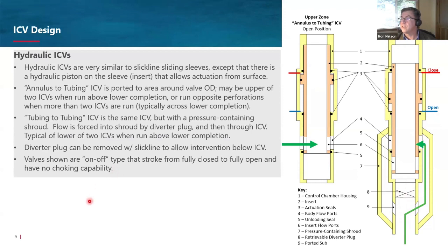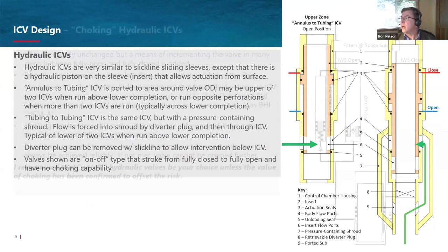So you still have vertical access to the well. What I'm showing here are on-off valves. They'll stroke from full open to full close with a pressure pulse. There's nothing limiting their movement. But we also have what we refer to as choking ICVs.